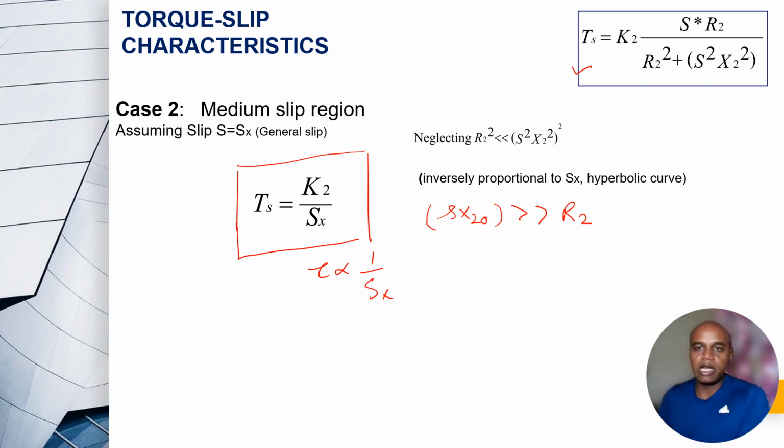So the induction motor has the capability for short time overloading. In case it happens, the induction motor can bear the short time overloading. Therefore, it gives 2 to 3 times the full load rated torque as maximum torque. Similarly, my starting torque of the induction motor is 1.5 times my full load rated torque. However, overloading protection should be deployed for the induction motor in case the overloading persists for a greater period of time.